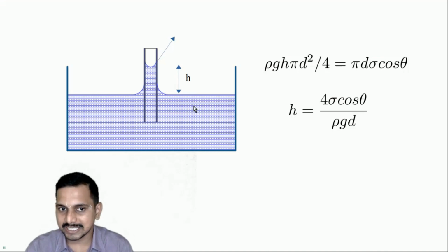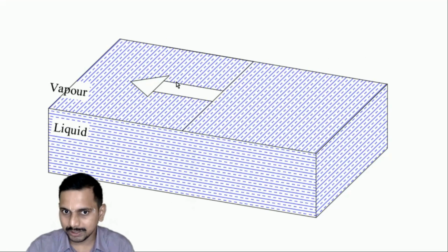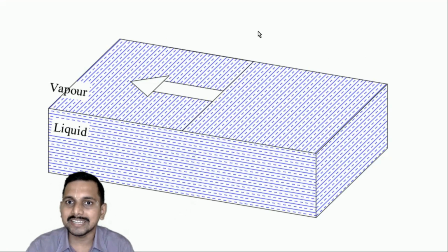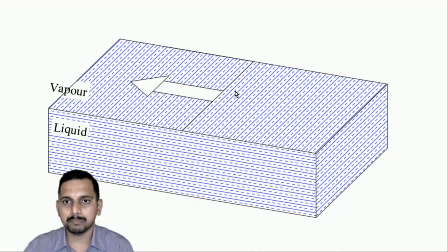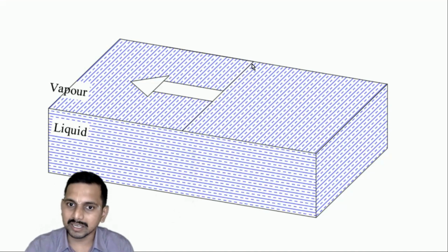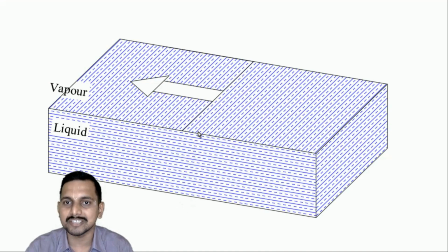Okay. Now, let us understand this again. See, Newton per meter length, that is the cause of surface tension. That is how surface tension is also measured. Surface tension is measured by pulling out one sheet from water surface, and we will see what is the force which is required. So, the similar thing, Newton, the force required to pull 1 meter of a surface. How many newtons required to pull 1 meter? That is surface tension. Okay.